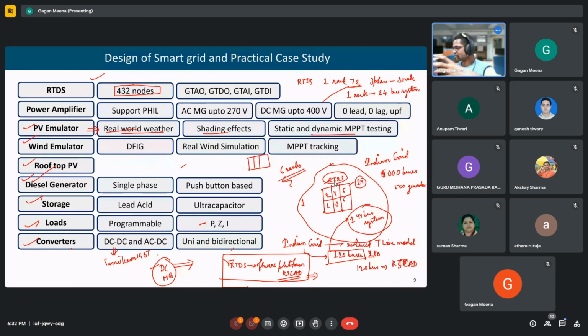In that case, the cloud may not always be covering the entire solar farm area. Sometimes the cloud may cover a few panels or a portion of the entire farm. So what will happen? The output of that portion will reduce, and that sometimes has other adverse effects. To reduce the shading effect, and to maximize the output from the solar panel even while there is some shadowing, dynamic MPPT algorithms are used.